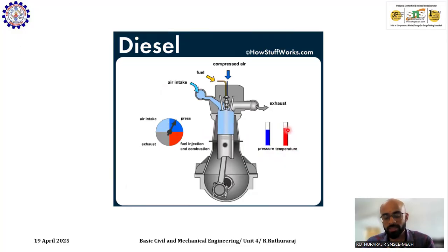So there will be high temperature air inside the combustion chamber, and once the fuel droplets are released into this high temperature air, they start to burn rapidly. So combustion takes place. The purpose of the fuel injector here is to inject the diesel inside the combustion chamber. Once it is injected, it burns. The air-fuel mixture will burn and combustion takes place.